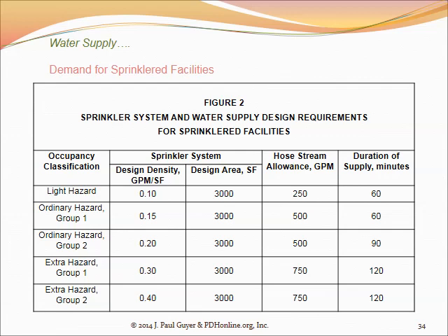And then, if you did the calculation, that information goes to the water utility. The water utility has their methodologies to see if their system of distributing domestic water around the community is adequate to supply this quantity for this period of time. And if the answer is yes, then you just get your fire water from the utility. If it turns out that the utility comes back and says, no, we can't supply that quantity of water, then what you have to do is store water on site for fire protection purposes.